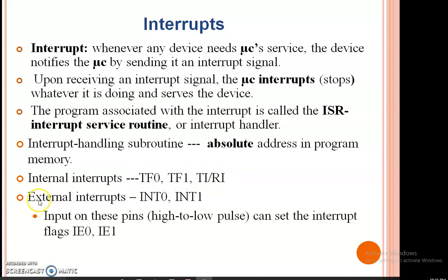And the next type is external interrupts. We have the INT0 and INT1 pins in the pin diagram. Using these 2 pins you can connect 2 external devices. Those external devices can interrupt the 8051. So these are called external interrupts or hardware interrupts.